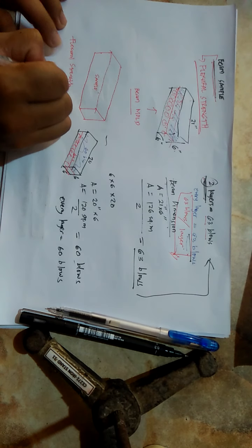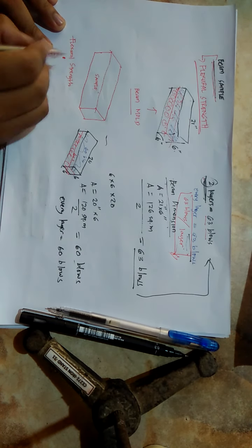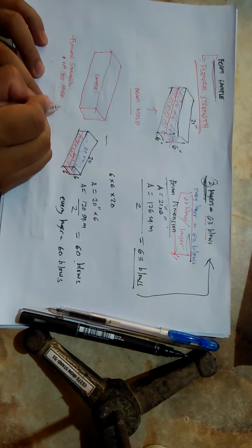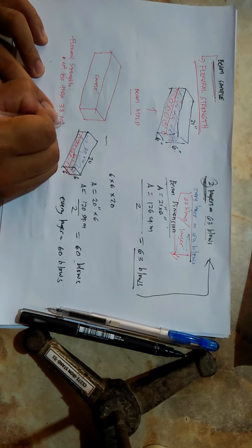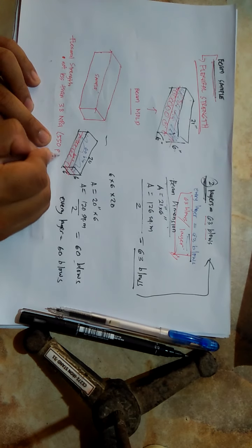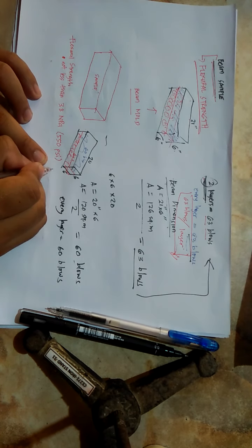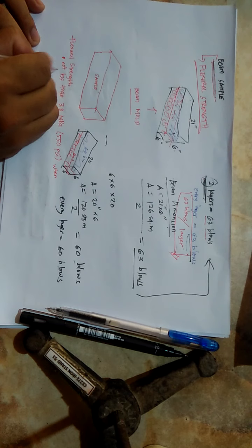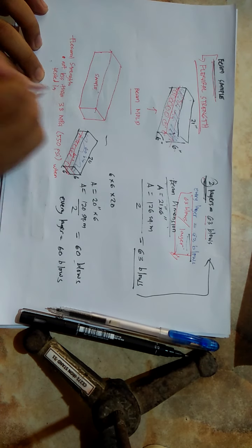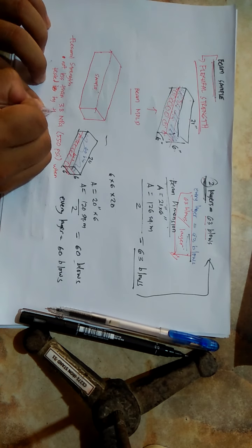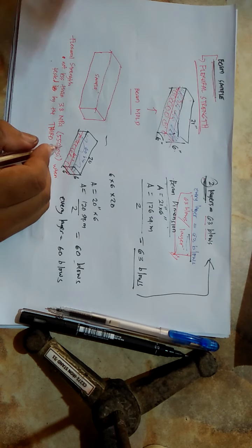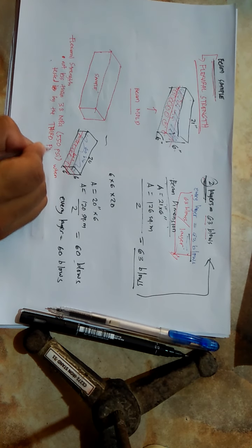Meaning to say, dapat ang flexural strength mo dito not less than 3.8 megapascal, or this is around 550 psi when tested by the third point method.